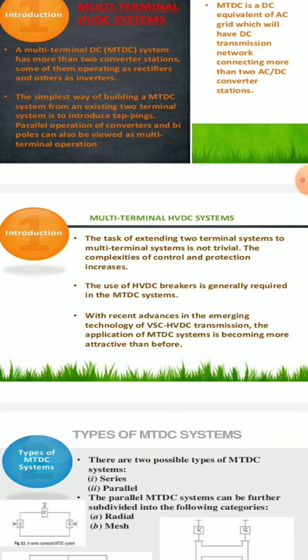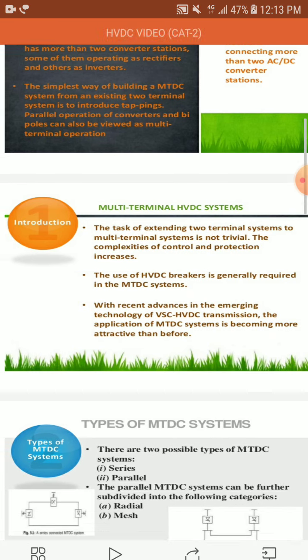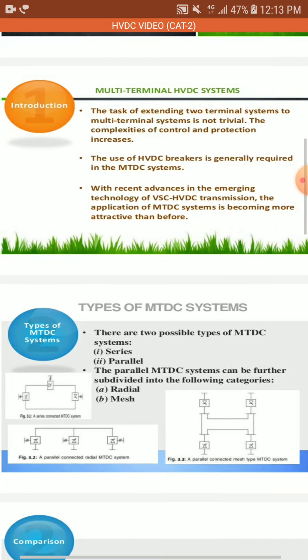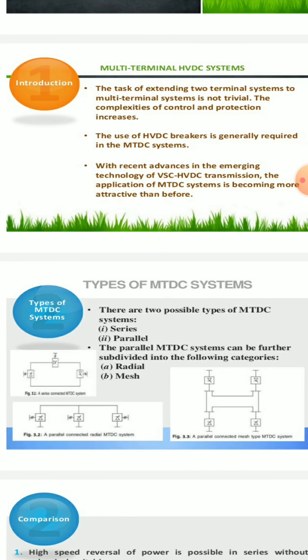The task of extending two-terminal systems to multi-terminal systems is not trivial. The complexities of control and protection increase. The use of HVDC breakers is generally required in MTDC systems. With recent advances in the emerging technology of VSC HVDC transmission, the application of MTDC systems is becoming more attractive than before.